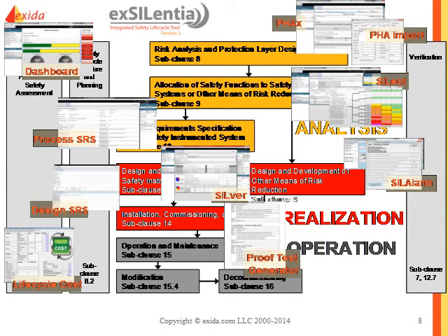We have a safety requirement specification tool, and in our case, we split it up into two separate tools: the process SRS and a design SRS tool. The process SRS documents all the requirements that come out of the process hazard analysis and SIL selection, everything you need to know in order to come up with a conceptual design for your safety instrumented function. That conceptual design is evaluated through the SIL verification tool, the Silver tool. And out of the Silver tool, we will have a bunch of requirements with regard to the detailed design of the safety instrumented function. And those requirements we document in the design SRS.